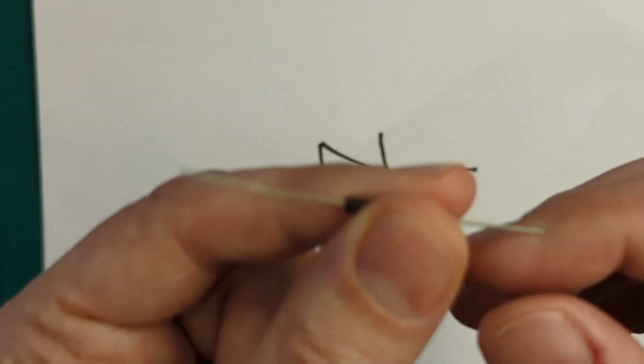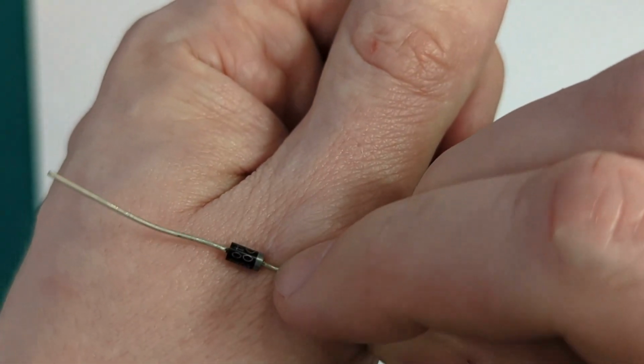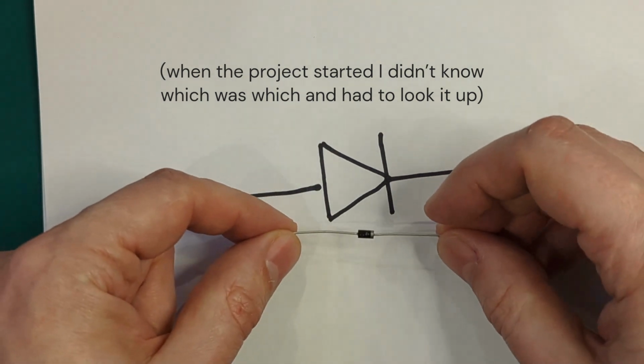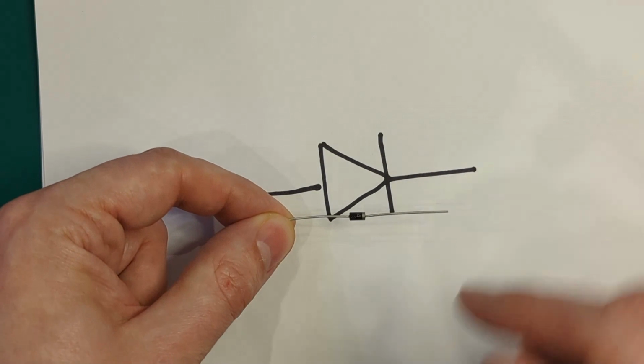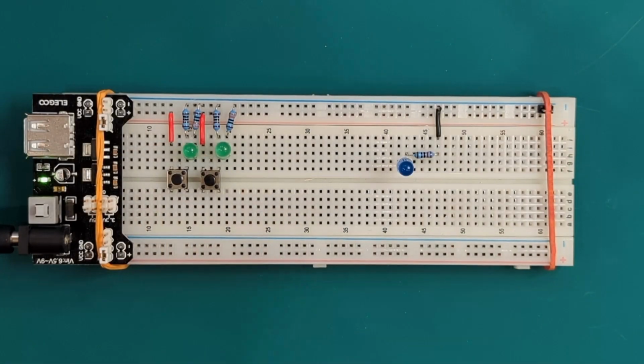So the color bar, or in this case like a silver bar at the end, corresponds to the pointy side of the arrow. And the most important of all, a diode allows current to flow only in the direction of the arrow. Let's test this directional property with a simple example.